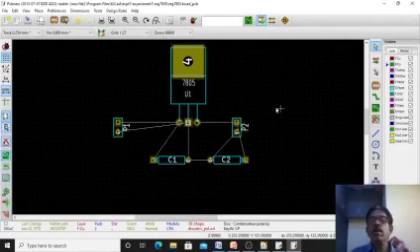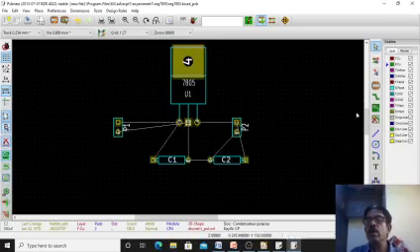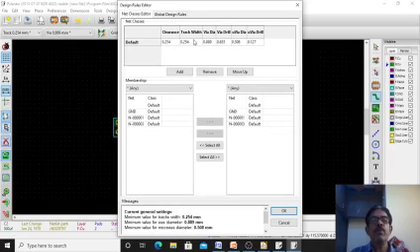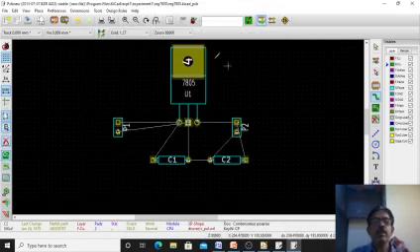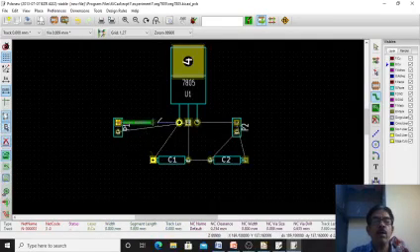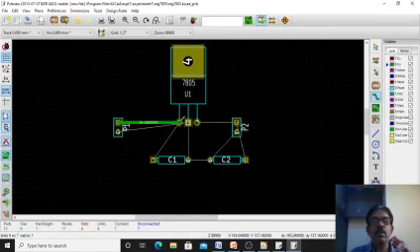So now put the copper wires on this. Okay, that is called add tracks. On this you add tracks. So already you go here, design rules, dimensions 0.254, it is by default. You select this and take a little bit higher. Okay, for example I will take 0.8 thickness. You take it, then go on connecting on this white wire, this tracks. Okay, you just see here I have connected wherever white wires are showing, you connect it.